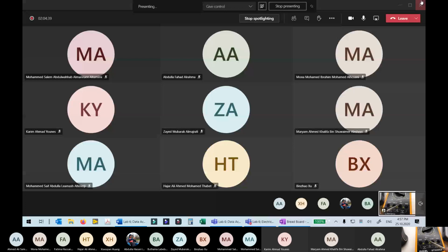You have milliamp and 20A, so these two are to measure current. You have several terminals depending on the measurement you want to do. For example, if I want to measure voltage, I'll plug one probe here and the other one into common.